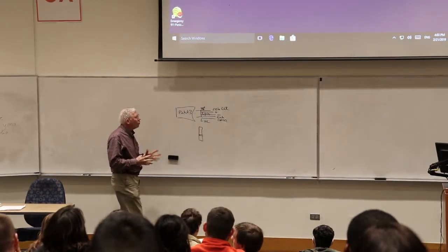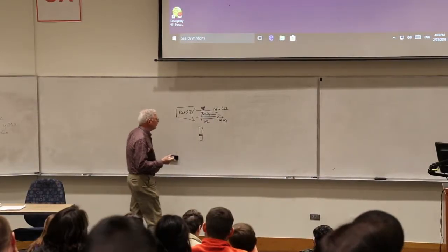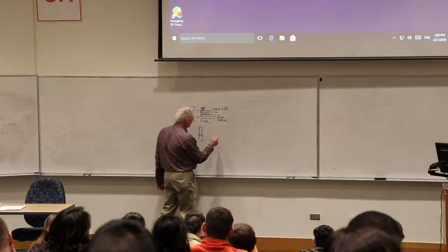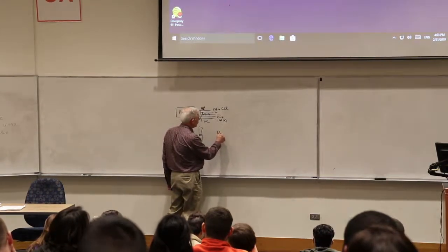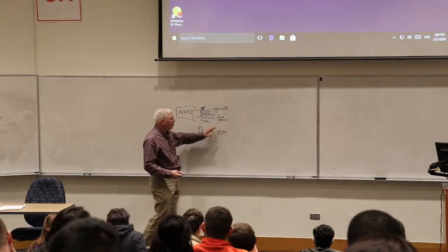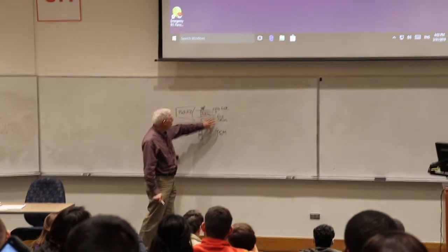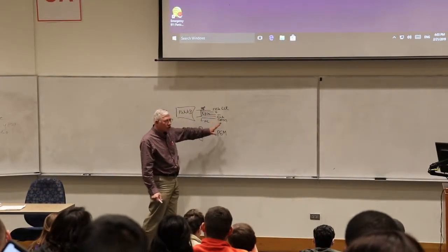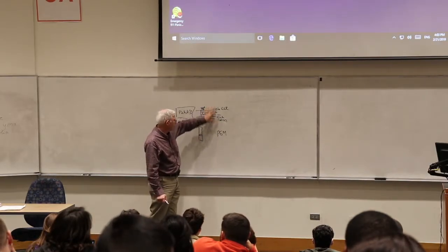In the old days, we had another pin that was involved in this interface, and I think it was called PGM or something like that. Nowadays, as the parts evolved, this program pin went away. So now the standard in-circuit serial programming and in-circuit debug interface is this interface.